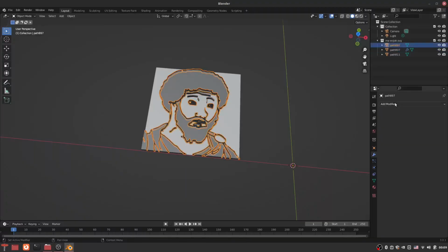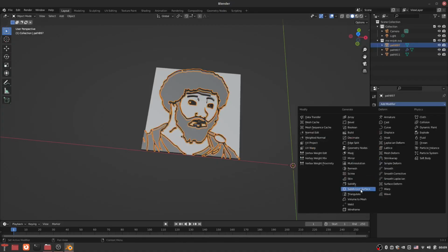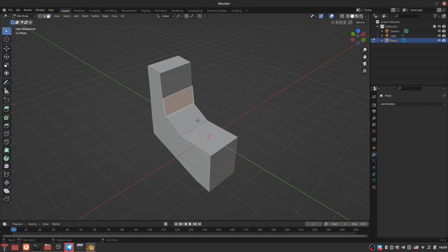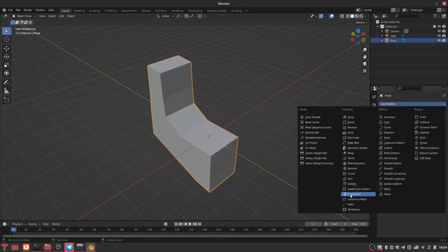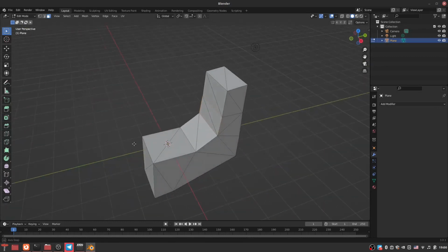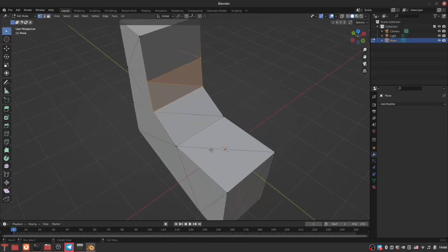Let's select the Triangulate modifier. It separates any non-triangle in the model into triangles. The thing is, for Blender, models made of quadrangles are most natural. The format into which we will export the model, however, likes triangles. You can actually make models out of any number of angles, so if you someday need to cut down on the number of angles in the whole model, use this modifier.